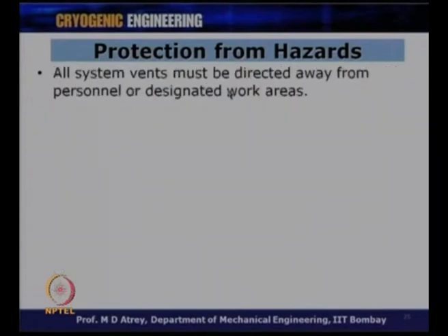All system vents must be directed away from personnel or designated work area. You should never stand across the vent. You should not stand facing the vents or the pipes. They should all be directed away from the personnel or designated work areas.